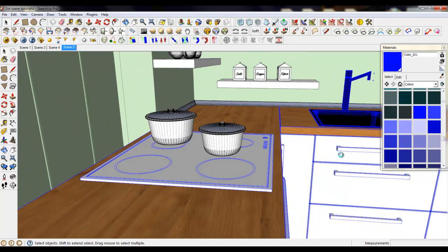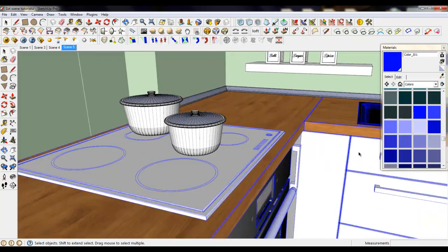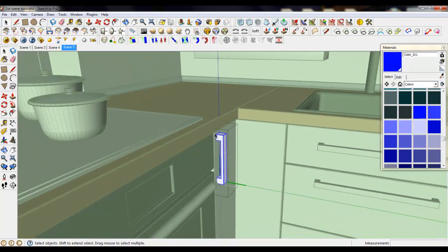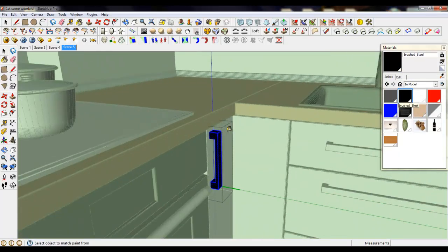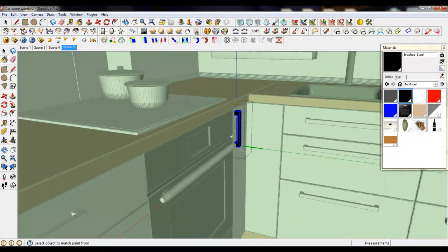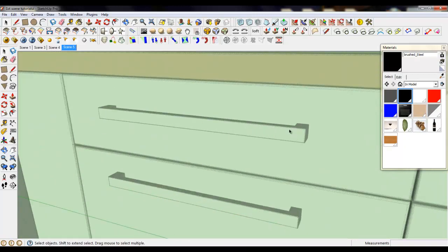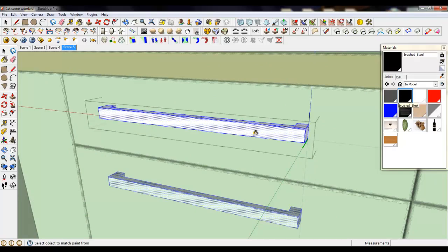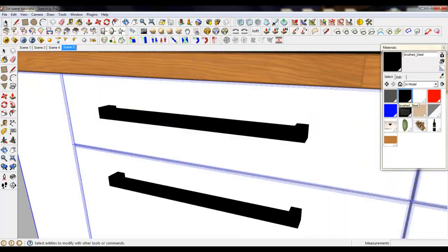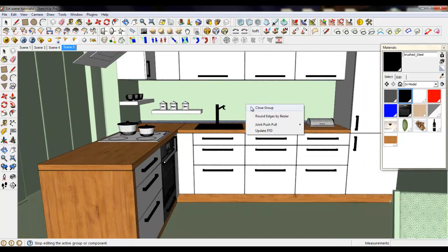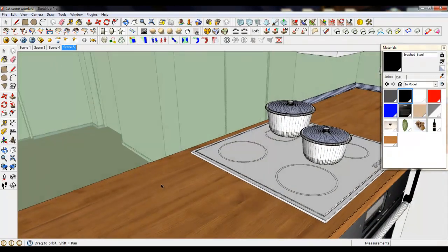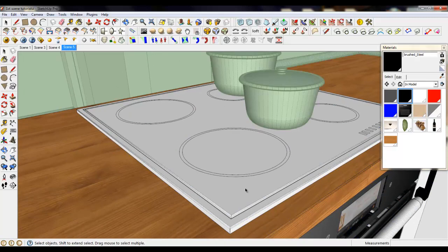material. The handles should be from metal, so let's add the metal material for the handles. Select everything, go to home page, select brushed steel and make it black. In render it will not look black, just in the SketchUp application. Select these handles to make them black.